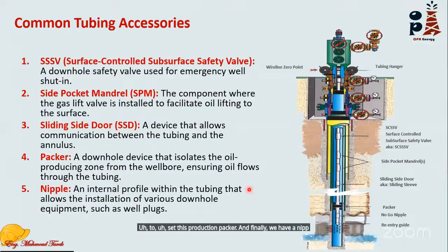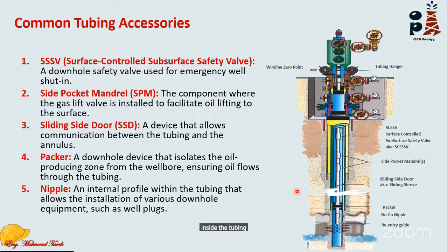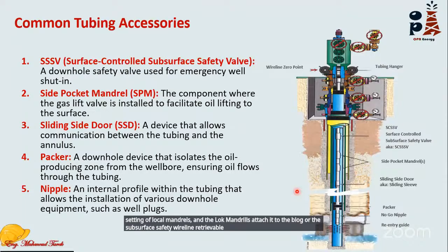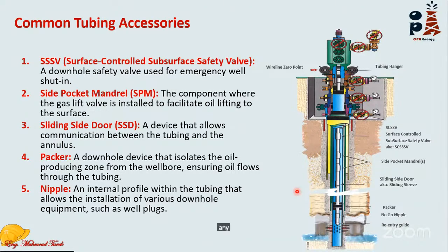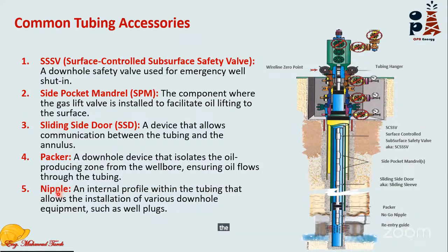And finally, we have a nipple. What is the nipple? The nipple is the internal profile inside the tubing to accommodate the setting of lock mandrels, and attached to the lock mandrel is the plug or the wireline retrievable subsurface safety valve, and so on. So any device or subsurface tool I want to hang inside the tubing will be hung inside the nipple, because it has an internal profile or groove to receive such devices.